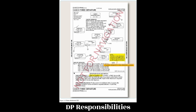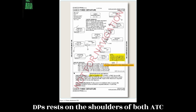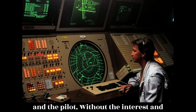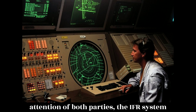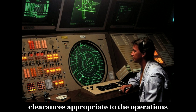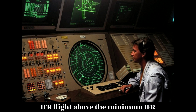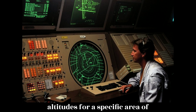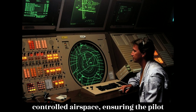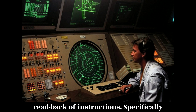DP responsibilities. Responsibility for the safe execution of DPs rests on the shoulders of both ATC and the pilot. Without the interest and attention of both parties, the IFR system cannot work in harmony, and achievement of safety is impossible. ATC, in all forms, is responsible for issuing clearances appropriate to the operations being conducted, assigning altitudes for IFR flight above the minimum IFR altitudes for a specific area of controlled airspace, ensuring the pilot has acknowledged the clearance or instructions, and ensuring the correct read back of instructions.